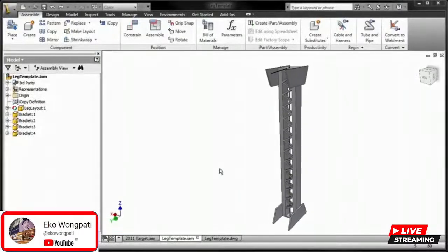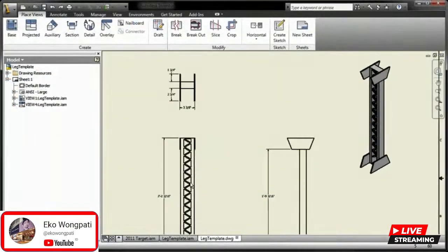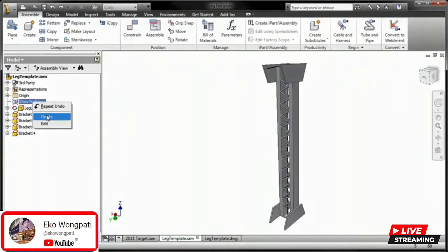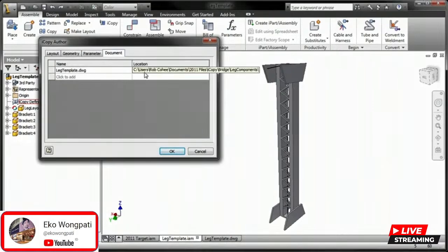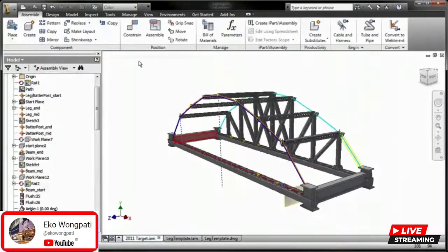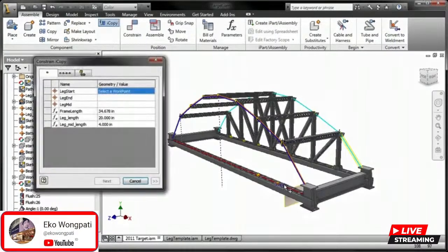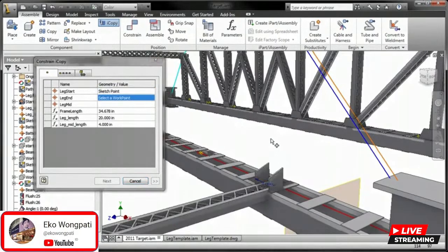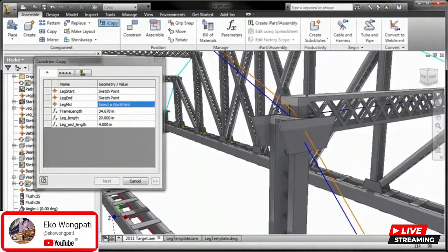Many designs require the creation of subassemblies which contain similar geometry, where only the size or position in the main assembly is slightly different. Instead of painstakingly adjusting the size of each copied element manually, use the new iCopy feature of Inventor to copy and resize your subassemblies automatically. iCopy enables you to easily customize commonly used assemblies by automating the process of copying and positioning similar components.